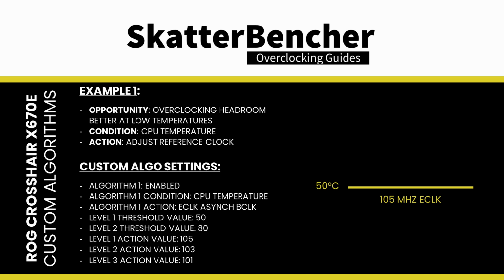When the CPU temperature is below 50 degrees Celsius, the reference clock is 105 MHz. When the CPU temperature is between 50 and 80 degrees Celsius, the reference clock is 103 MHz. And when the CPU temperature is above 80 degrees Celsius, the reference clock is 101 MHz. That gives us a performance increase of 5, 3, and 1% respectively.